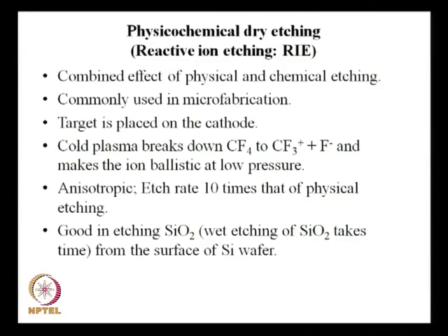Silicon dioxide, as I said, will form automatically. If you leave a bare silicon in atmosphere, the oxygen is there, that oxygen will react and it will form a nanometer scale layer of silicon dioxide. It will form automatically, okay, and that has to be etched. So, any etching you start, the moment you start the etching process, you have to first etch silicon dioxide and then etch silicon. And etching silicon dioxide is not that it's more difficult than etching silicon.